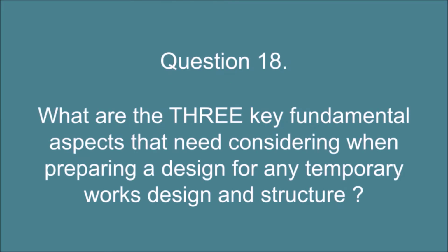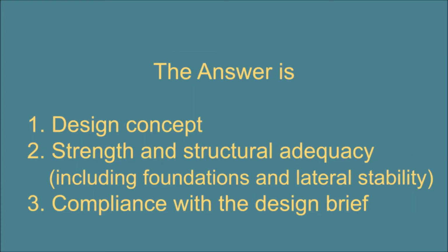Question 18. What are the three key fundamental aspects that need considering when preparing a design for any temporary works design and structure? The answer is: 1. Design concept. 2. Strength and structural adequacy, including foundations and lateral stability. 3. Compliance with the design brief.